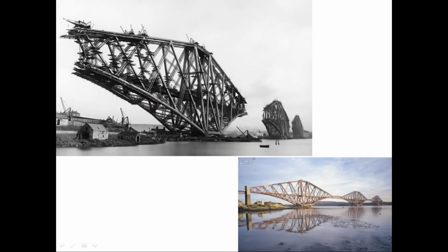The dead load on that side and the dead load on that side are equal, so the structure is balanced. So in fact it's a series of independent cantilevered structures, and these are just little links, little trusses, connecting the two together. They are not part of the overall structure. They are little miniature bridges, if you like, connecting the main bridges in the structure.